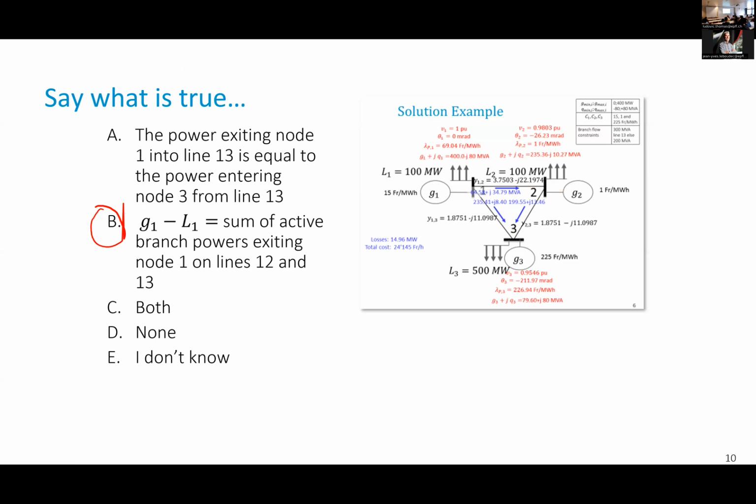And what you said is perfect, a very good observation. The slack bus function is to balance the system exactly. So if G2 and G3 inject some amount here, then G1 must be sure that the complete system is totally balanced. Now, whether the losses are balanced by G1, G2, or G3 is not obvious in this case. Here I've done a global optimization problem. I need some amount of power, and G2, G3, and G1 have provided this power. Who generated the power that's consumed by the losses is not so easy to say. This is the so-called attribution problem.